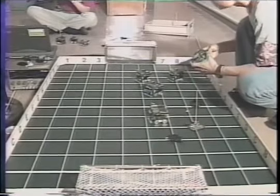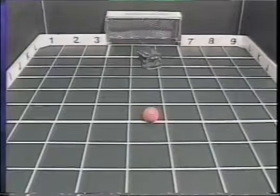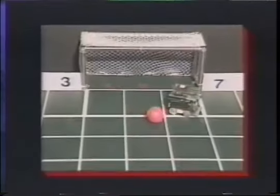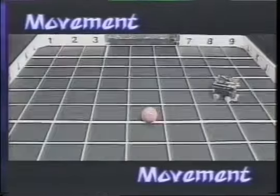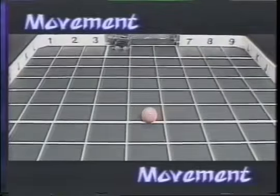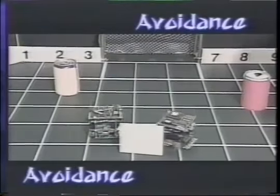The vision system can catch objects on the field and process to get their positions with about 1 centimeter error 10 times a second. It broadcasts this information to the robots. The robot has 4 basic behaviors: movement, obstacle avoidance, shooting, and blocking, and uses them according to the decision of a high-level controller. Movement behavior shows 3 motions like move forward, turn, and backward when the desired position is given from the high-level controller. The side sensors are for detecting walls and other robots except the ball.